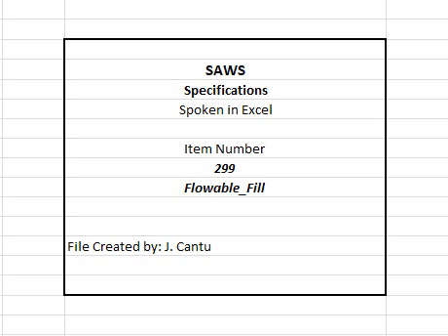299.7 Measurement. This item will be measured by the cubic yard of material placed of accepted work complete in place. 1. Measurement will not include additional volume caused by slips, slides, or cave-ins resulting from the contractor's operations. Payment. The work performed and materials furnished in accordance with this item and measured as provided under measurement is for